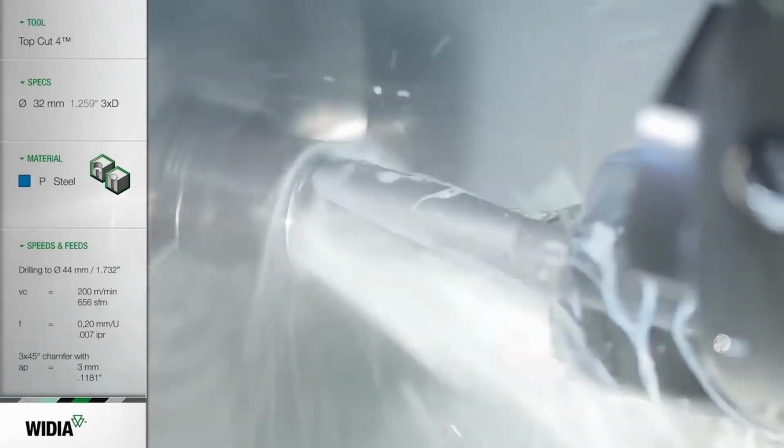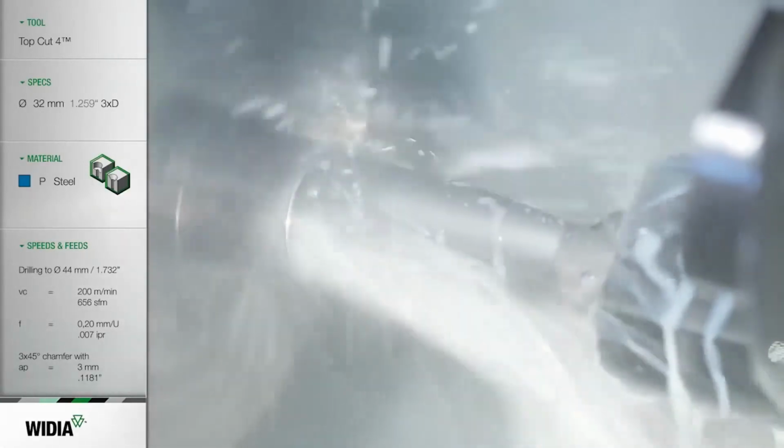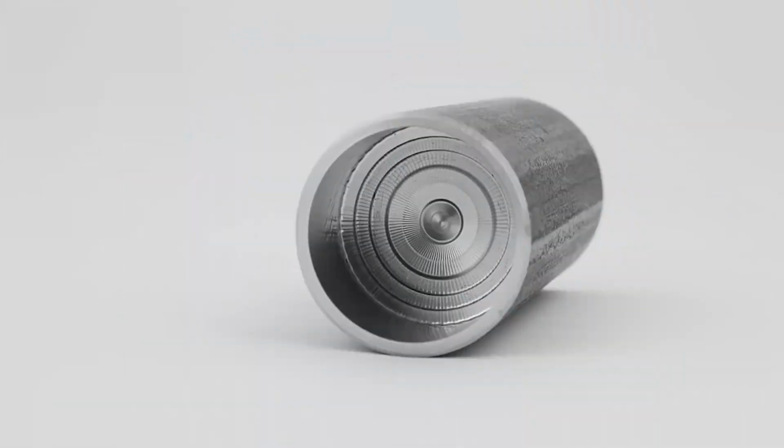The shorter the tool, the better the results for internal turning, and the chamfering in the end. So you can produce conical holes, because in most cases you have a CNC turning machine, and you can program the movement to make a chamfer or conical hole.